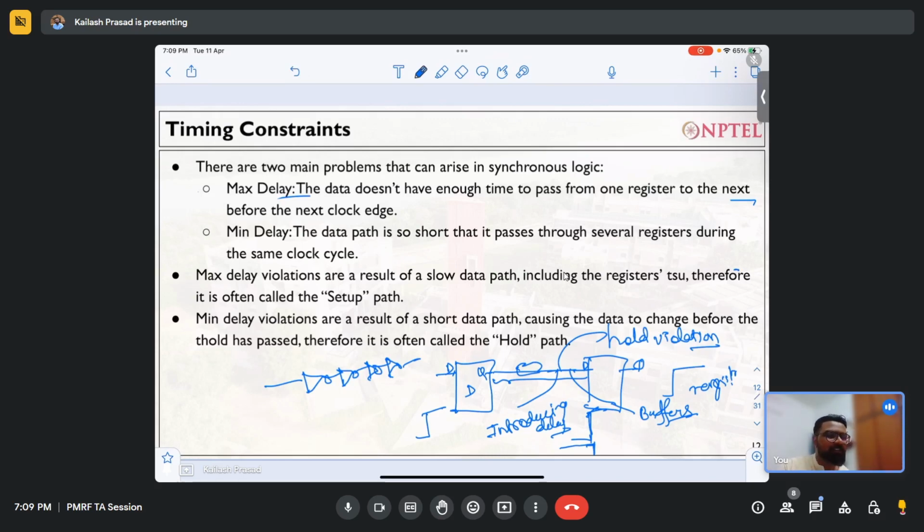So this was not the famous interview question. The famous interview question is, you have made a chip out of it. You have fabricated everything and made the chip. Now you found out that there is a hold violation. How do you remove it after fabricating it? You cannot change the hardware. Can anybody tell me? If you detected it at the software level, it is good, you add the buffer and change it. But what if my chip has the hold violation?